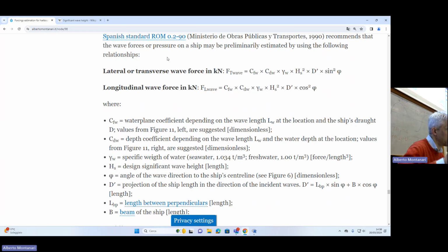Each of these two components is assumed to encompass everything, because with waves, actually, you don't have drag. With waves, there is no movement of mass unless they break. Within a harbor, we suppose that the waves don't break, it would be a problem. So the waves are not associated to a movement of mass. It's just a movement of energy.